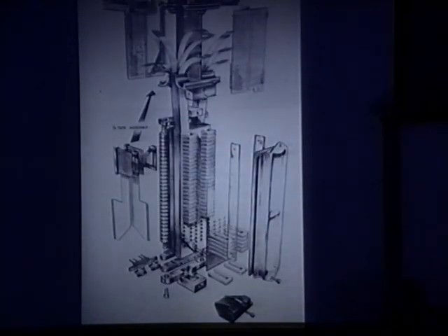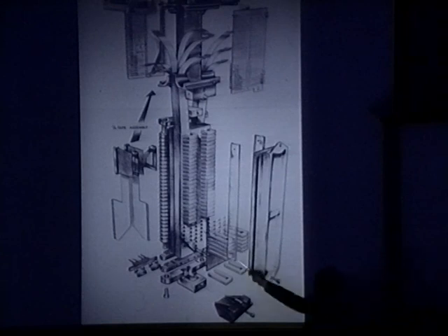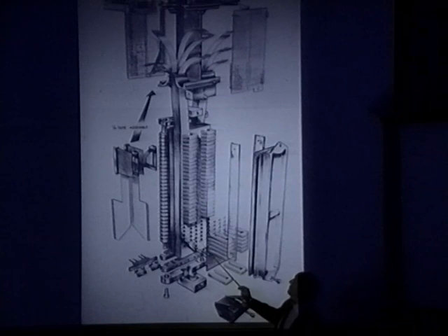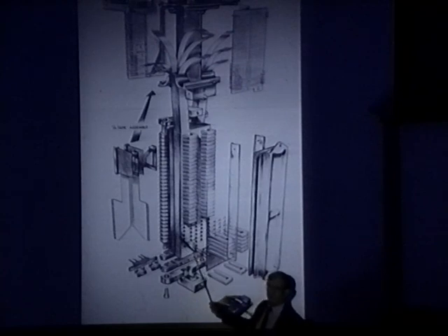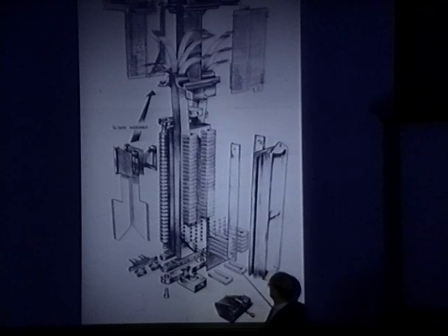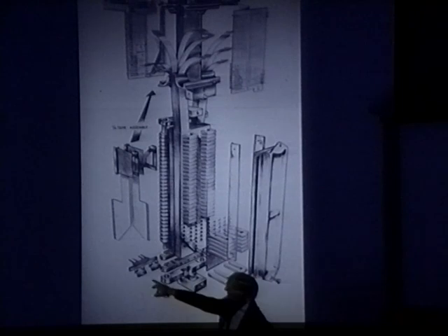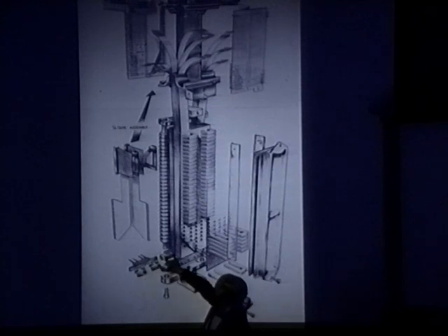Because the printed circuits take up more space than the wires, here are the tapes carrying the word wires. I believe, by the way, this is a very early example of flexible printed circuitry. We discovered we could really not get more than 128 tapes. There are the transformers. Here are two of them that have been removed. The I cores which mate with these U cores are here, placed in this carrier, which is contained on this frame.